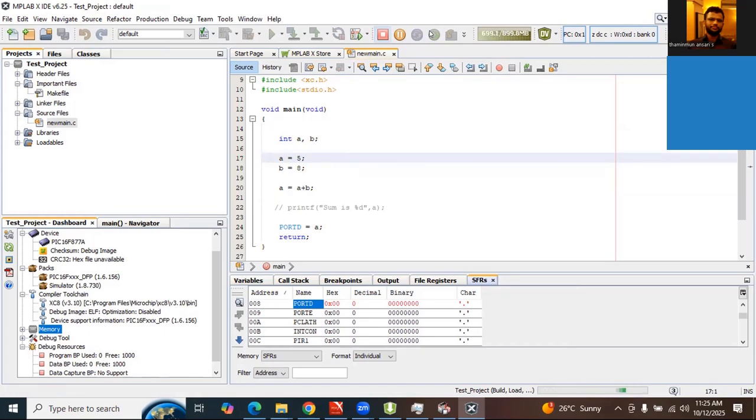In general purpose programming, we use the PC monitor to see the result. But here we are using particular port pins to see the result. Even here we are just using a simulation. In real, if you convert this program to hex and flash it in our real microcontroller, those particular pins will go to different states based on the computation result.